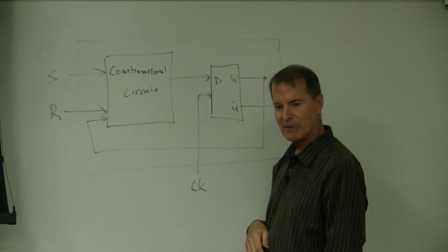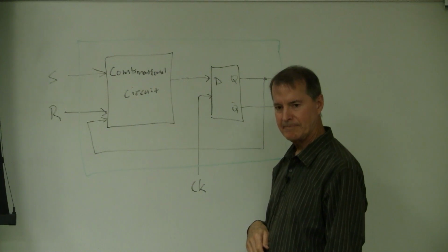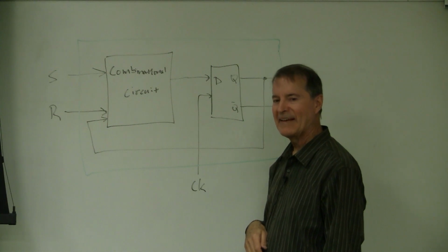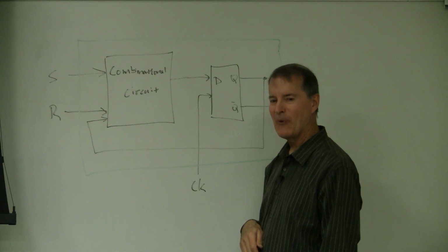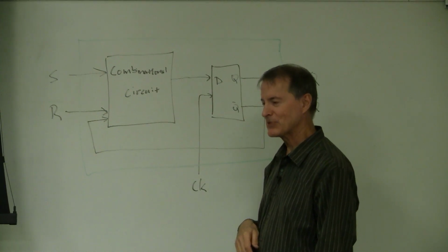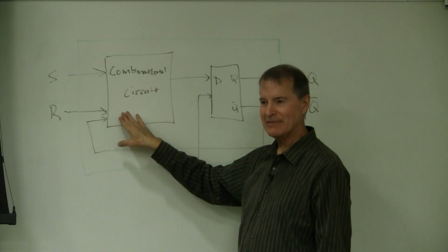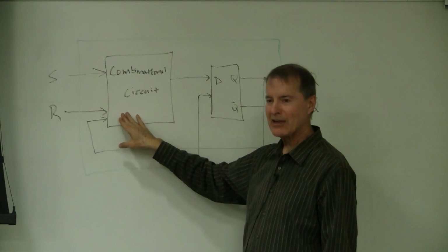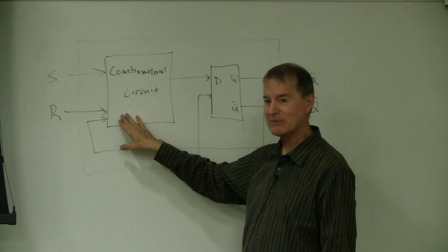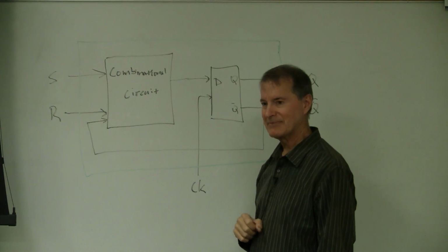And what was your question about whether you did something illegal? Yeah, so I was making the table where I have Q, S, R, Q(t+1). When it's 1, 1, I put an X in the Q(t+1). That's absolutely right. Because look, you're trying to make an SR, right? It's undefined what it is when it's 1, 1. So that's a don't care condition. So in your minimization, take advantage of it. Cool. That was a good question.